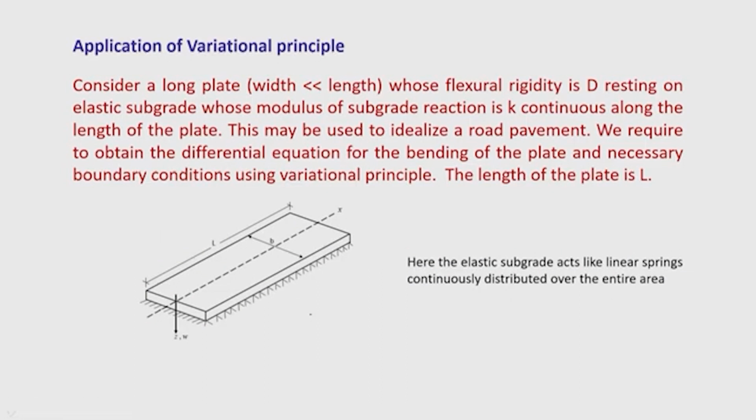Consider a long plate. I am taking a long plate, width is very less than length, whose flexural rigidity is D, resting on elastic subgrade whose modulus of subgrade reaction is k, and the subgrade is continuous. The plate is supported over the subgrade continuously, there is no break of this support.